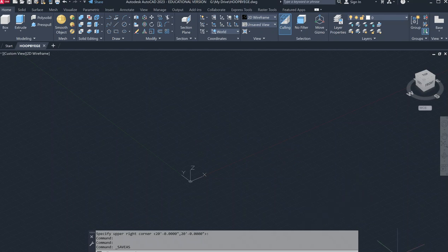Also, I want you to pay attention to my precision tools at the lower left-hand corner. Okay, and you have to have Object Snap blue. If it's not, click on it, please. Grid has to be blue. Okay, Object Snap is off, so it's gray. The grid has to be blue, which is pressed. There is something called dynamic input. It should be on, blue.